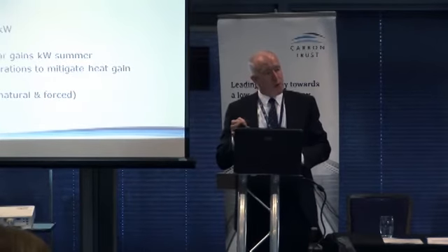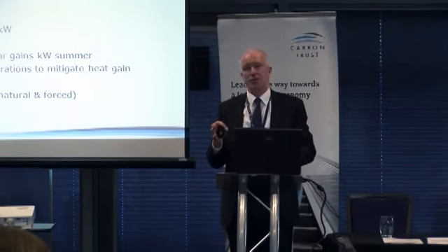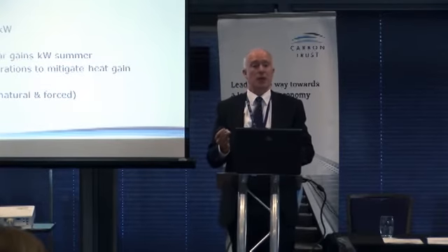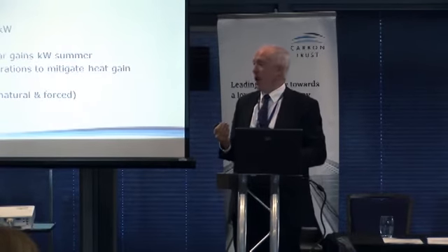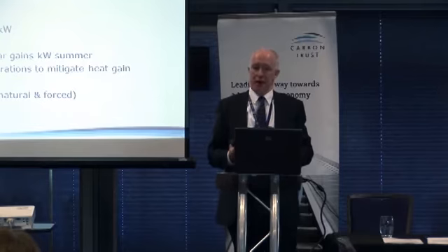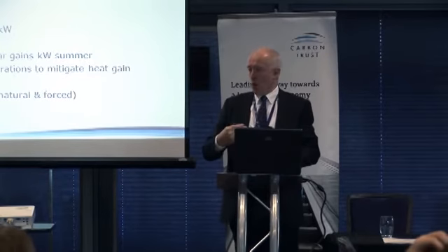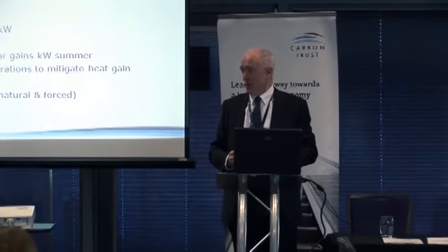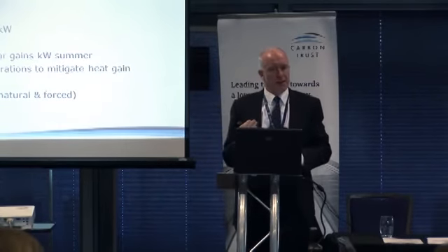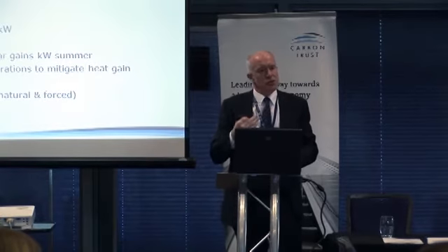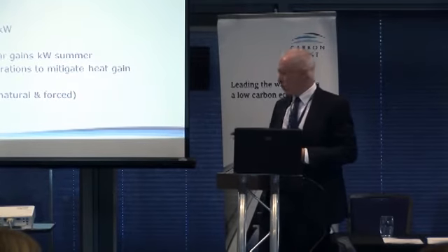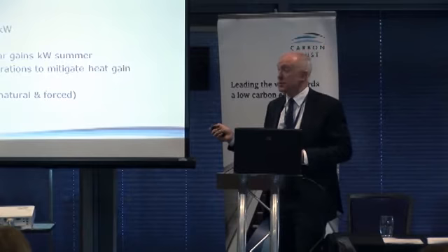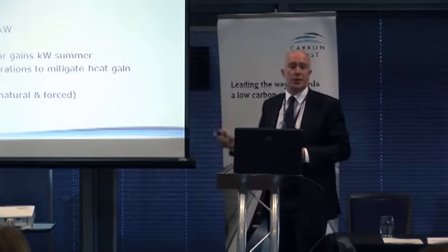IT is also a component of heat gains to our offices, and quite frankly, we are not going to move greatly on climate change unless we get rid of air conditioning. If we have all our offices air conditioned, all our factories air conditioned, it's not a clever thing to do. So we must avoid air conditioning like the plague. And in order to do that successfully, we need to reduce our heat gains to less than 40 watts per meter squared within our buildings.